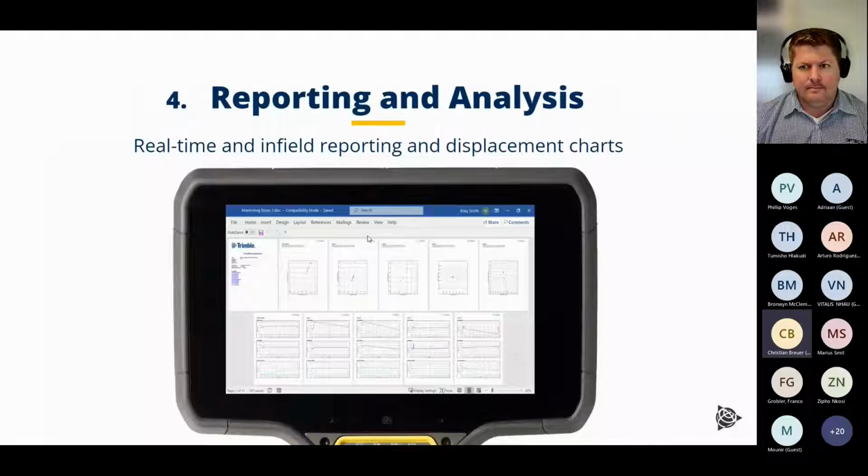daily or weekly whatever observations, in the field directly you can create multiple reports, including such Word documents, which then can also include not only the values of the displacement but also graphs. You can see here scatter plots for horizontal movement, or individual graphs for northing, easting, and elevation displacements. Okay, we are talking about Trimble Access and Trimble 4D Control Access Edition.